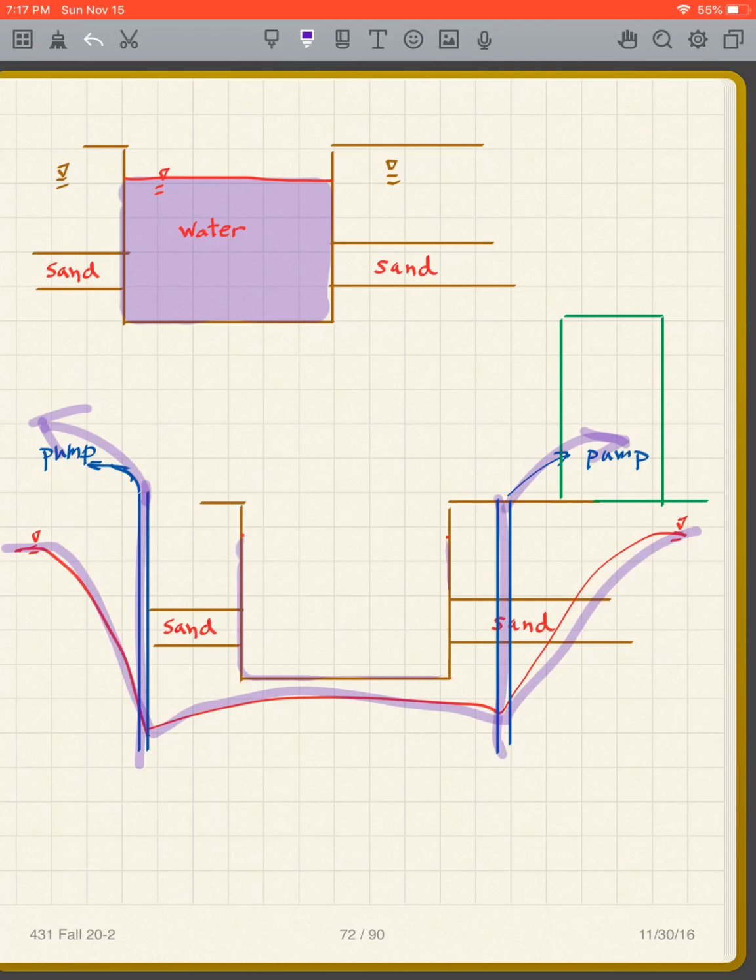What I'm doing is I try to lower the water table below this sand here, obviously, and make sure, well, I need to pump through the sand as well. I need to make sure. And you may need to cut things off here, to make sure that you can keep the water level down.